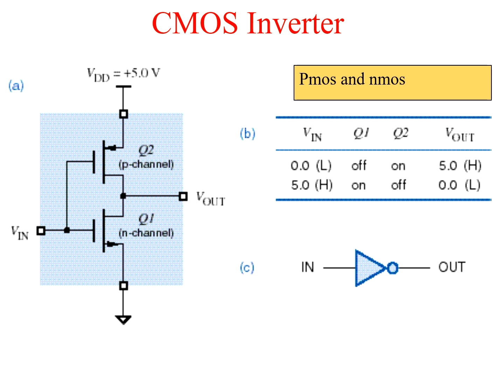And this is a circuit diagram with the values. The input voltage is 0. Transistor 1 is in the off condition and transistor 2 is in the on condition. At that time the output will be 5 volts, that is high voltage. In the next condition, when we apply high voltage, that is 5 volts, transistor Q1 is in the on condition and transistor Q2 is in the off condition. So at that time the output is 0, low voltage.